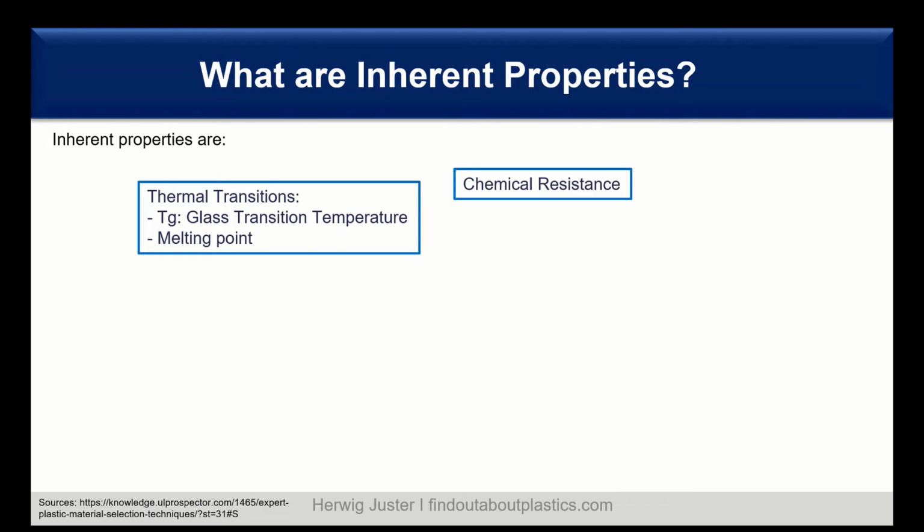And for example, we have heard before about stress crack resistance, and here when the material has a bad chemical resistance, it can then also trigger the stress crack. So this is called environmental stress cracking. So one can then lead to the other. So you can have a proper design, however, when the chemical resistance is not enough, then you still end up in stress cracking situations.